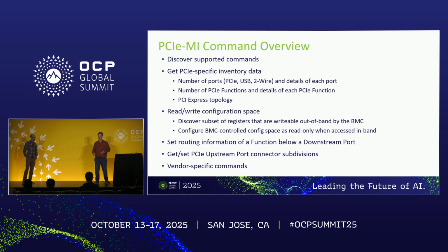So what's in that command set? The command set, of course, has discovery, so you can discover what is supported on the device. Then you can figure out where the ports are, so you can find the different ports that all get to the same piece of silicon, because a lot of times there are two, three, four ways into the same piece of silicon. And then a very important thing is read and write of config space. This lets you take a lot of things that were traditionally done in band and shift them out to other management entities, primarily a BMC.